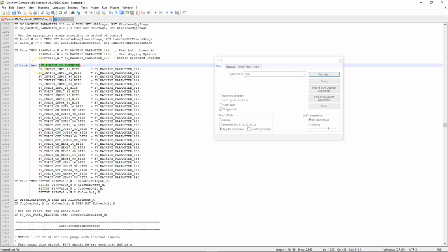But if you've got it in coils and then you've got other logic somewhere else in the PLC program, that will compete, and chances are you'll either never get that thing to turn on, or that outcome will start flashing on you. Because as I said before, it goes through every single line. Once it gets to this, it looks at this condition, says yep, that's true. Then it keeps going down the line to the other line of logic that's turning it off or doing something else, and it will do whatever it needs to because that condition is also true. So this might come on for a short period of time, or it'll just flash, turning on and off, on and off, on and off.